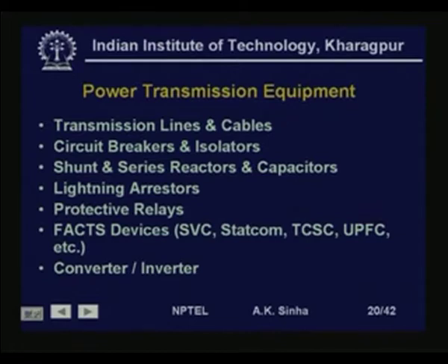We have other devices like shunt and series reactors and capacitors. These are basically reactive power devices: reactors consume reactive power, whereas capacitors generate reactive power. So, in order to maintain the voltage profile in the system, we put these capacitors and reactors at various places in the system.